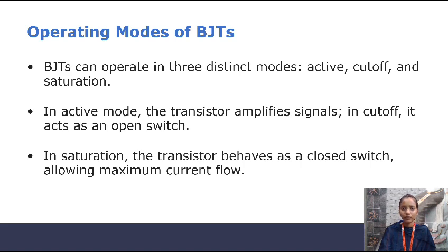Here in active mode, we connect input section in forward bias and output section in reverse bias. In cutoff mode, both are in reverse bias, and in saturation mode, both are connected in forward bias.